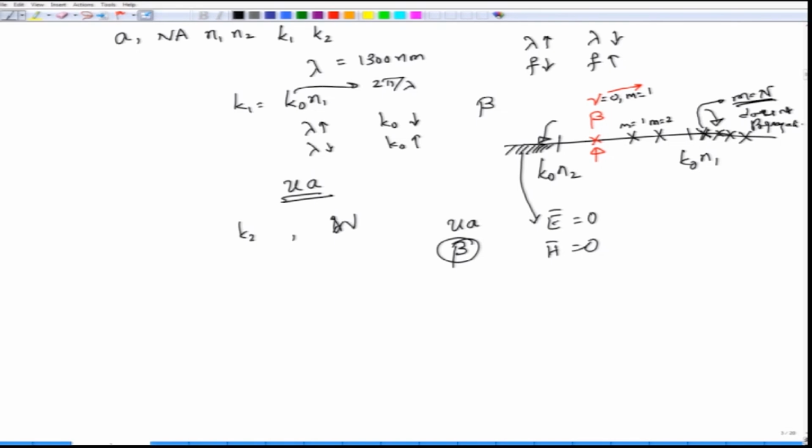Okay. So that mode does not propagate. Now let us go back and look at the modes that we have. We have TE0m, TM0m, EH and HE, both are nu times m. Nu can of course be equal to 1 here, and nu is not equal to 0, because when nu is equal to 0 you get these two modes. Now let us ask this question, what is the lowest order mode that is propagating?